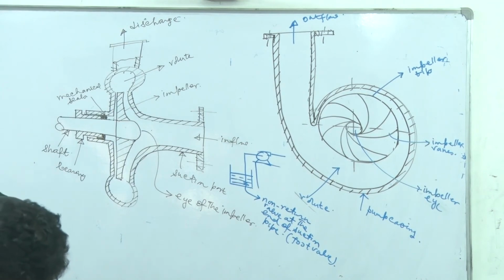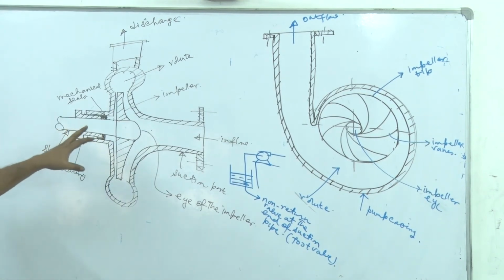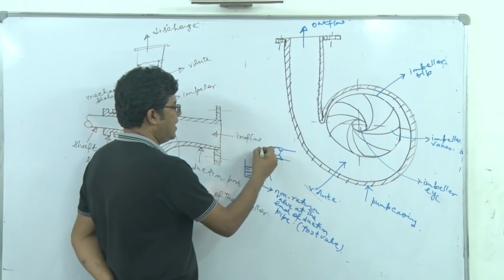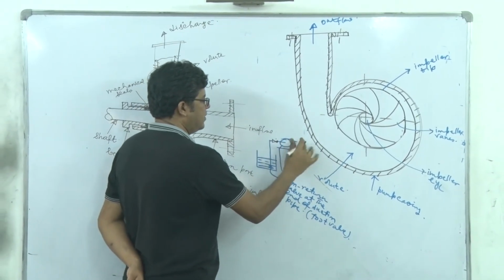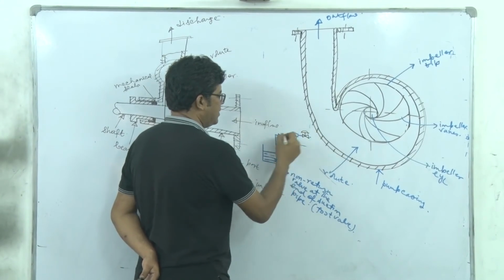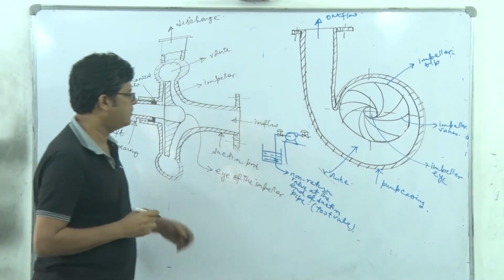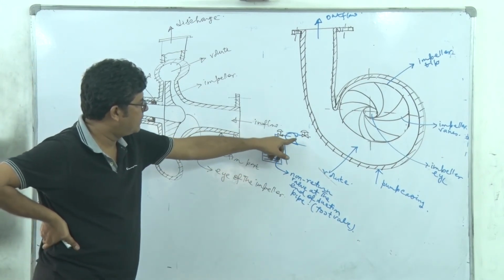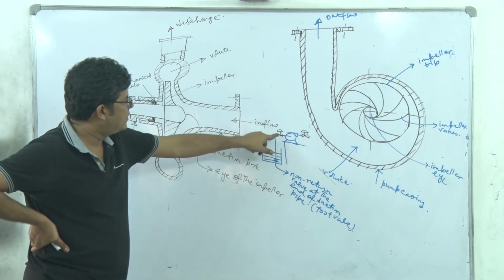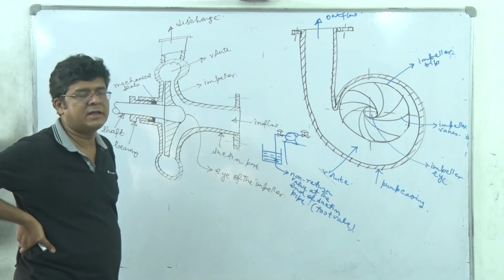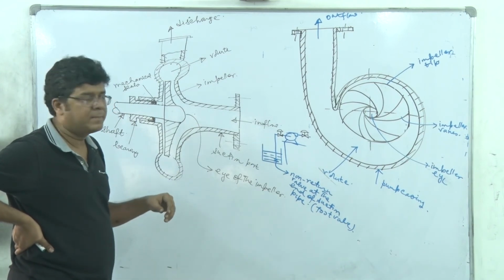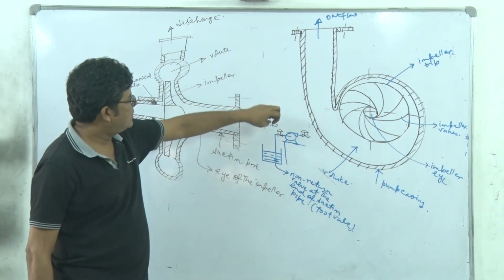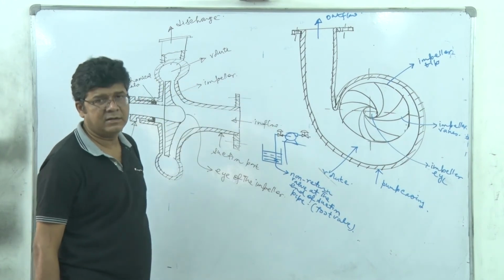Now you see that before we start the motor, here maybe we have a valve, here also we may have a valve, right? A control valve, like all this. So we have to ensure that the entire pump casing and the suction line is filled with the liquid to be pumped. Why is it necessary? Because when the impeller rotates, this will definitely create a head.